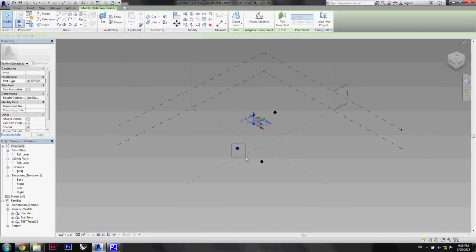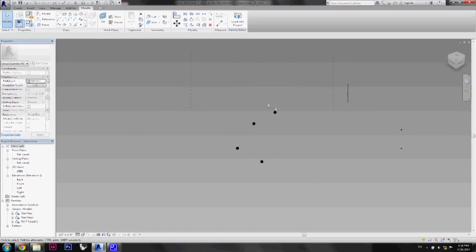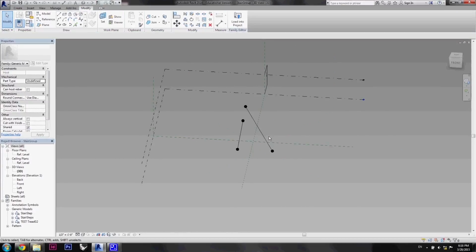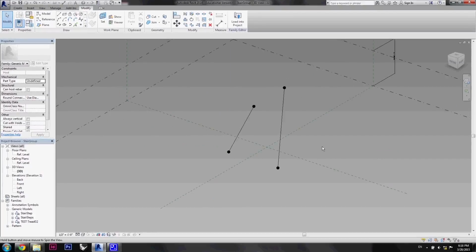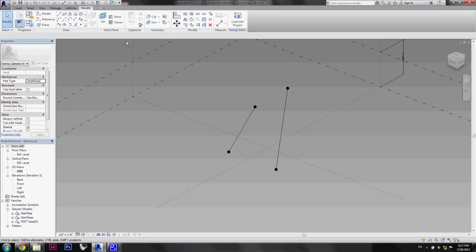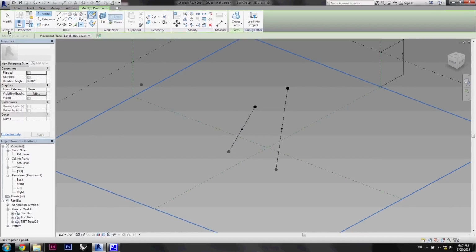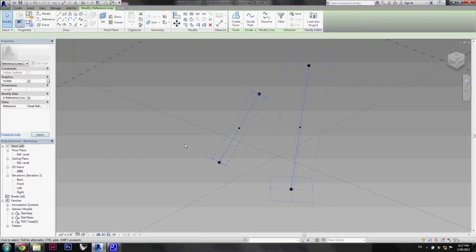And now we are building the edges of the staircase, which is also controlled by 4 points in 2 levels. And now we just make the connection between each 2 of them. We want to make the curved edge, so we need to first know the middle point between these 2 points, then offset the middle point a little bit, and redraw the line, actually the curve.